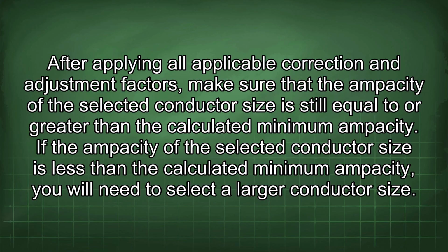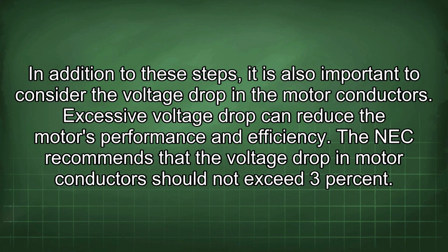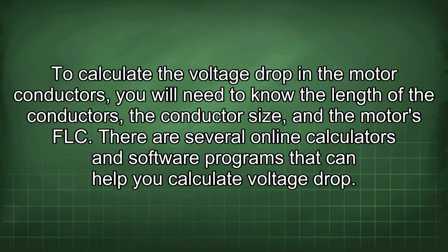a larger conductor size. In addition to these steps, it is also important to consider the voltage drop in the motor conductors. Excessive voltage drop can reduce the motor's performance and efficiency. The NEC recommends that the voltage drop in motor conductors should not exceed 3%. To calculate the voltage drop in the motor conductors, you will need to know the length of the conductors, the conductor size, and the motor's FLC.